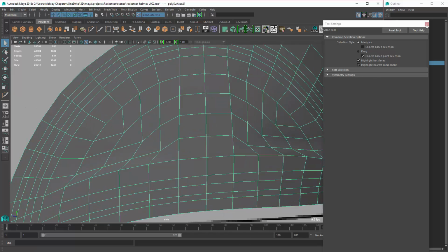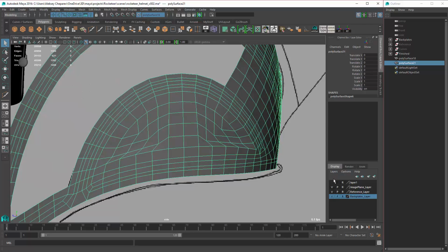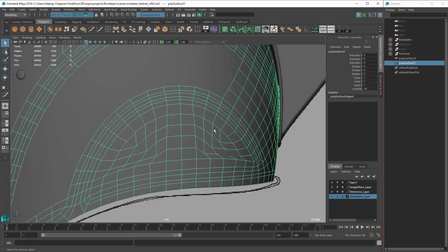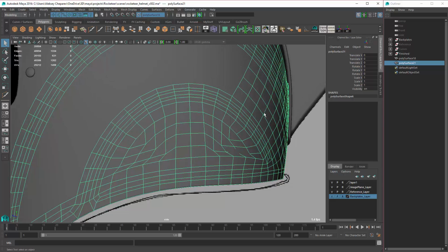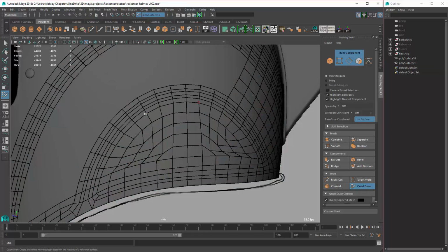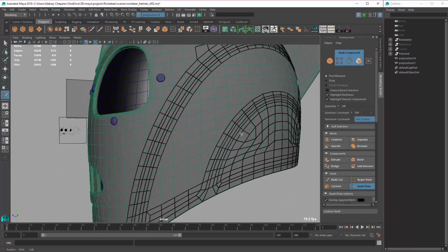So now all we need to do is make the object. I'll bring back this layer. I just added our live object to the layer, which makes it easy for me to hide it. And then once you select the object, all you have to do is click Quadro again, and it will turn it into a Quadro mesh. And then we can just start spacing these out, and as we do this, they'll start to snap to the surface.